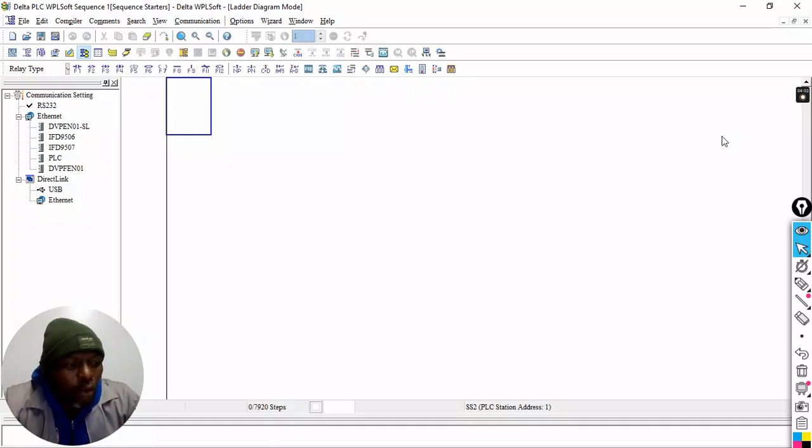However, overload should cut the circuit immediately. I don't agree with that part. I cannot even do that part, because this is two different motors. It is electrically illegal to use one overload for two different motors. It can be, maybe by design or coincidence, that the two motors have what?